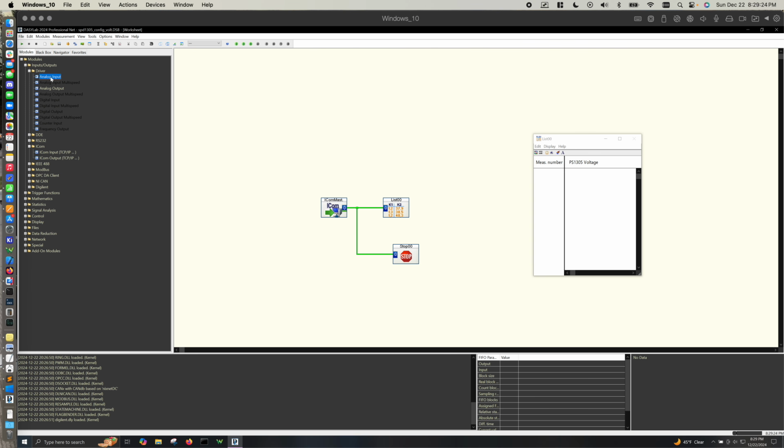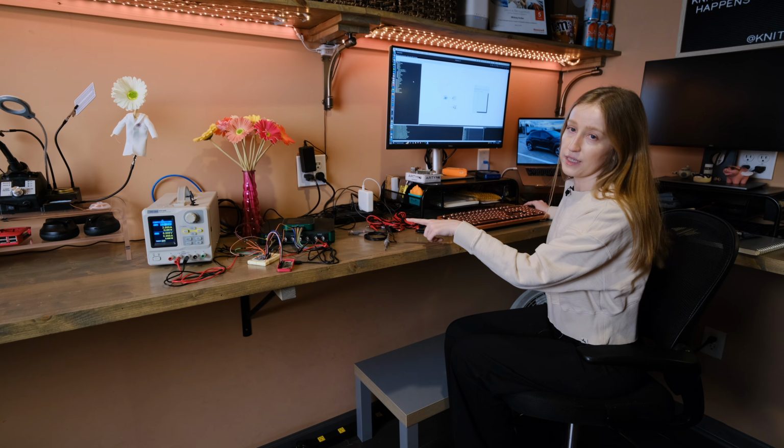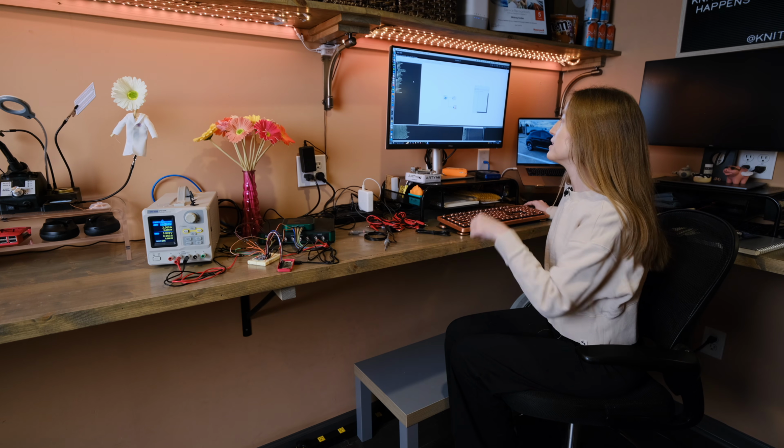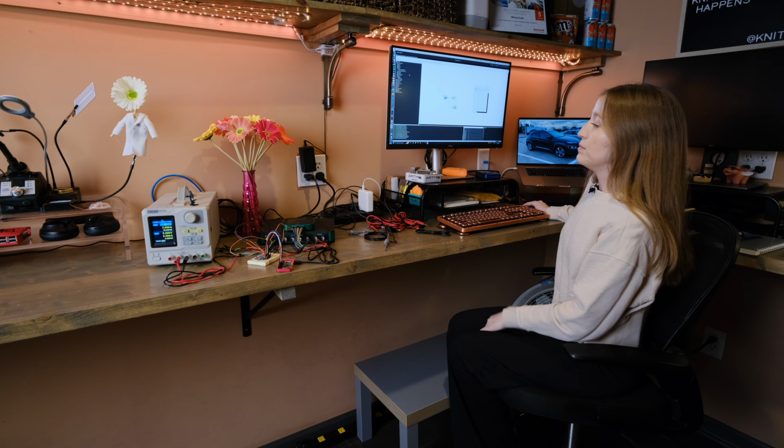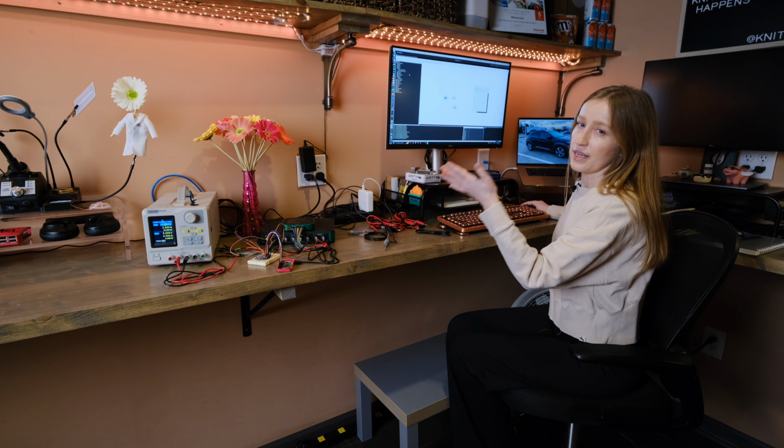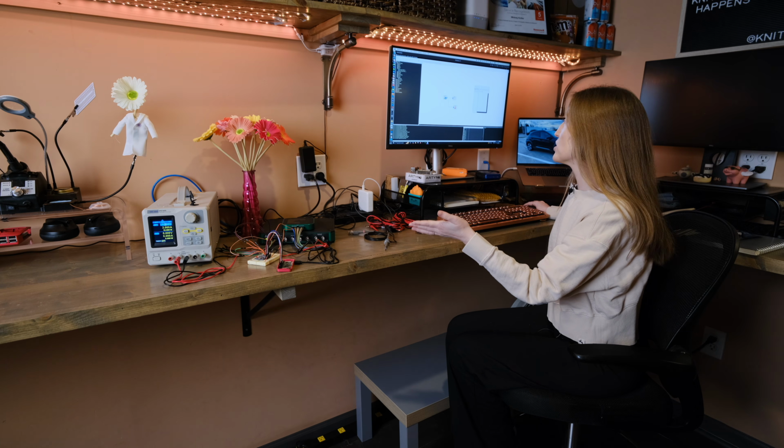And then if you install any extra drivers like NI device drivers, those will appear here as well. Like my NI CAN driver you can see is here, as well as Digilent with the AI record to talk to the Analog Discovery devices. So like I said, I'm just opening up a port and sending SCPI commands to my power supply.